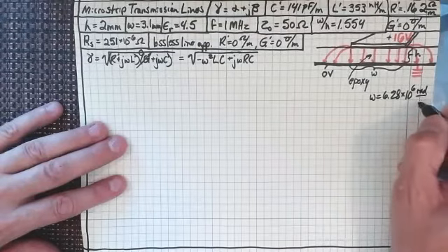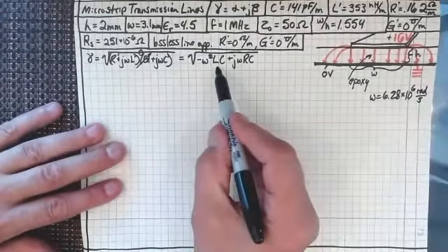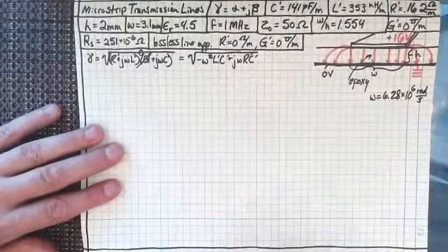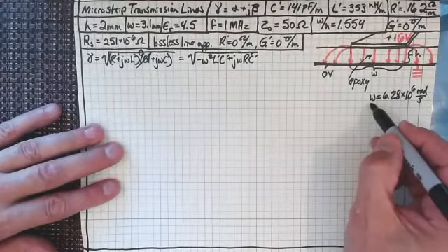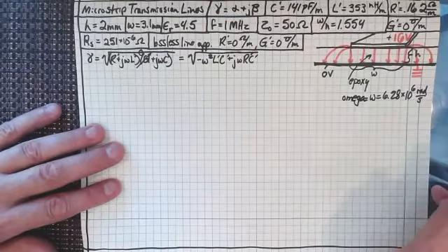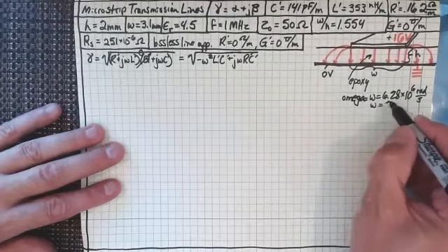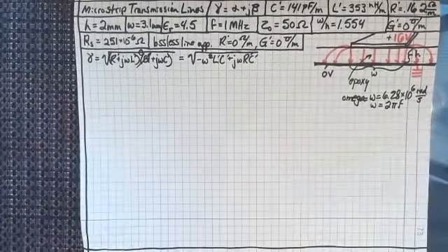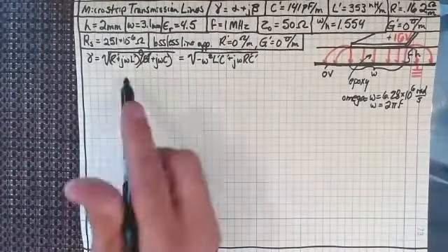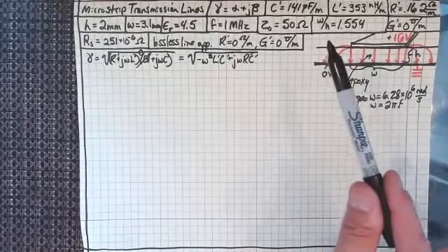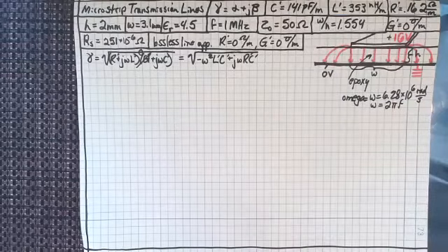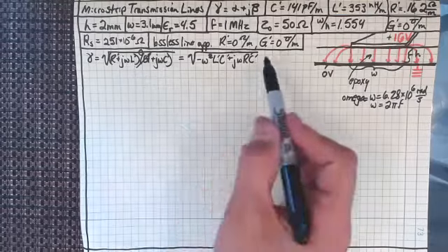radians per second. And we've got L prime and C prime and R prime and everything up top here. Now this is omega, remember, I'm just going to write this because I don't want you to get omega in your notes confused. Omega is 2 pi f. In your notes, you can look at that. This is omega, but in the equations that we use to solve for L prime, W over H ratio, and the other things, we all used W. This is not a W, it's an omega, right? So we've got all those.